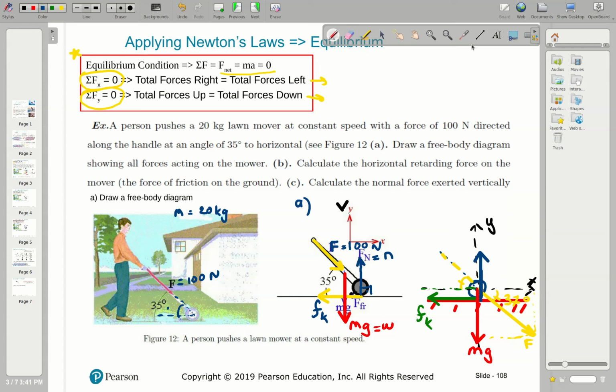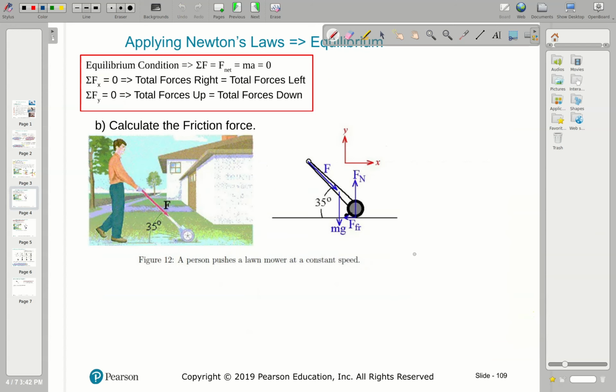It's kind of a mixture of carrying everything to a point and drawing on the picture to help me see what's happening here. Use your own method. I've seen some of you just drawing a point at the origin and showing all the forces there. It's all good. If you want to imagine the situation a bit, what's happening there physically, you can draw this. But what we do eventually is carry all the forces to the origin, which should be this one here, and find the total force. That's my free body diagram.